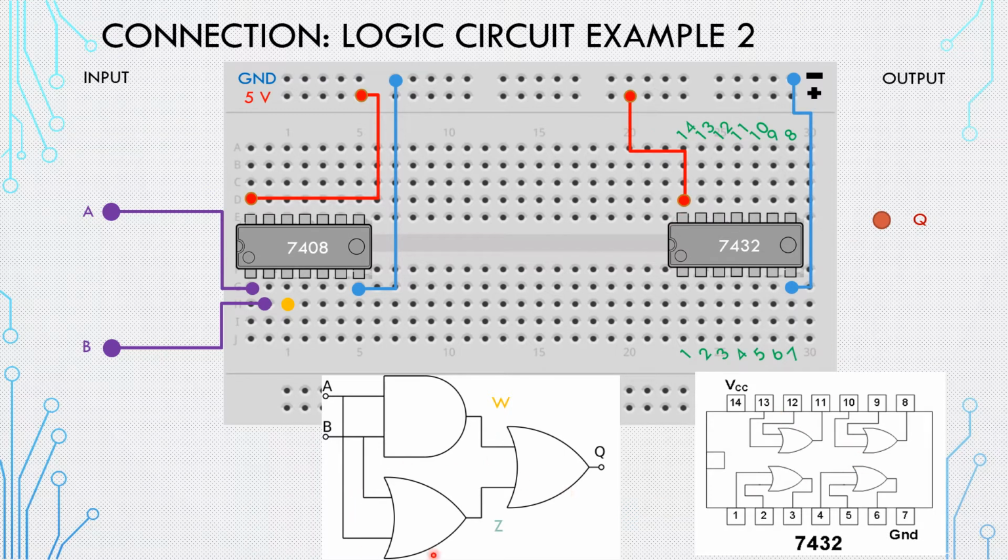Now I want to connect this gate, the OR. What's the input for this gate? One's coming from B and the second coming from A. So you can take B directly, or you can take whatever you place at this line. So this line becomes B. Since you put B here, this line becomes B. So you take wires from here and connect it to one of the gates inside the IC.